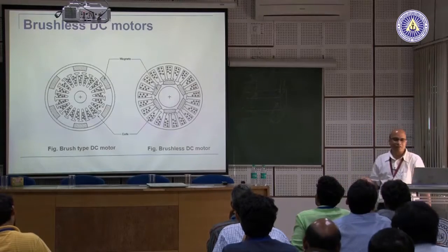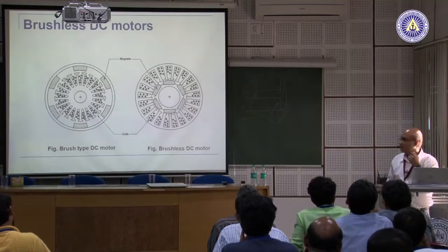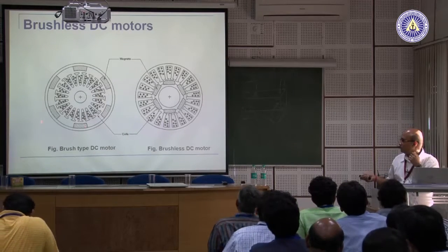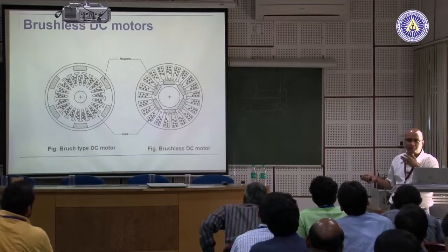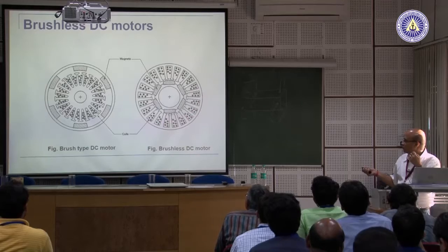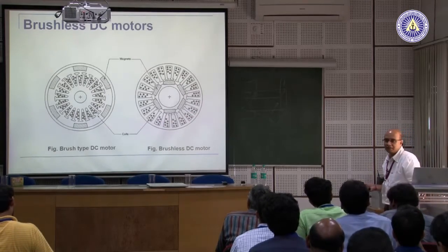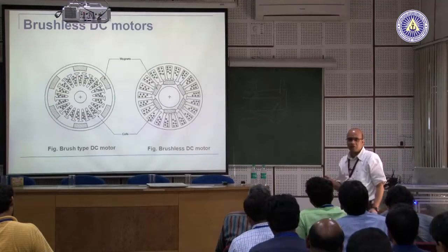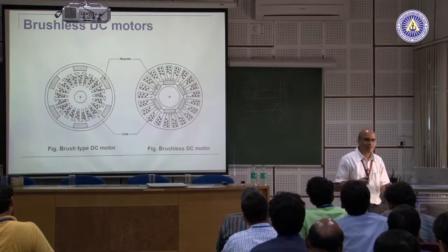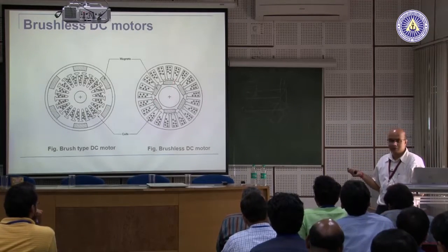Now, most industrial automation devices like robots and NC machines use brushless motors, because a brush motor has less life because of the brush. So, all the devices in automation normally use brushless DC motors, and brushless means that the cost is very, very high, and that is also where the cost of the robot comes from. The links, the nuts and bolts and screws and wires probably do not cost much, but essentially it is the actuators which cost.